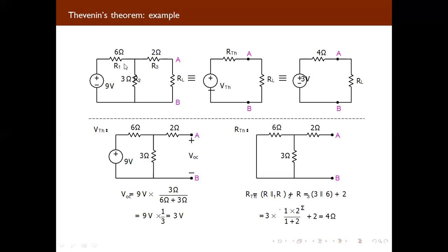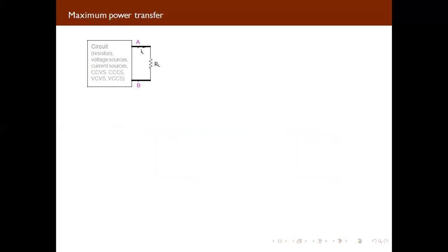Here we can convert the Thevenin circuit into Norton's, or we can solve directly for the Norton's. How can we solve? If we are having any complicated circuit, at that time we can convert that complicated circuit into a simplified circuit where we will get the value of shunt current and the value of Thevenin resistance that will be in parallel. Here, instead of voltage there will be current, and here the resistor will be in parallel. And if there is a load, you can consider it as it is at the output. So what does the maximum power transfer theorem say?